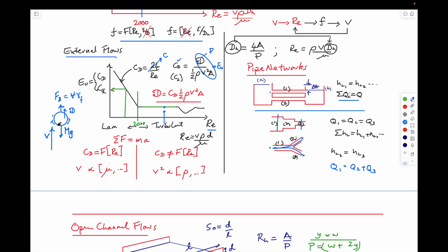If you're solving for a free body, then you have to account for the velocity of flow past that body and the forces acting on that free body. There'd be three. There'd be a drag force, D, due to the coefficient of drag, which we've just talked about how you calculate. There'd be a weight of the body as mass times gravity.